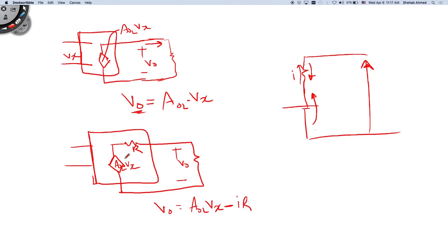So ideally you want that to be 0. And input impedance, I want it to be high. Because I don't want current coming in from my sensor to be high at all. I want it to be as low as possible. I just want to measure the voltage basically. I want to take that and amplify it. And I want at the output to consume as much current without changing the level of voltage that I have at the output. So that's why input impedance high, output impedance ideally 0.